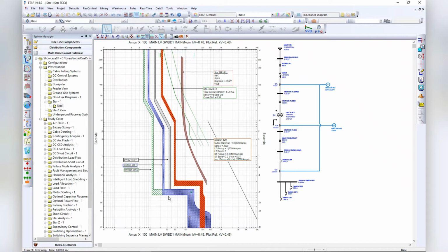and we have to assume that they are coordinated with whatever is on that drive cabinet. So that's the standard current coordination. No extra feature. We are doing all our flash calculations based on that standard coordination.